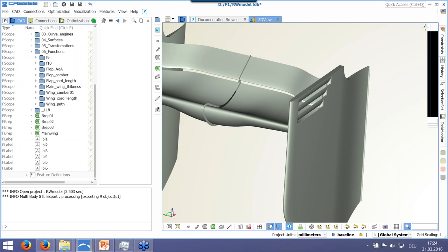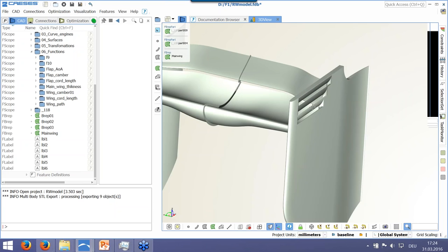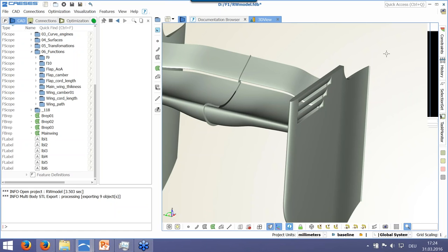Okay, and why we use these louvers or these slots here is because when you open these slots, a quantity of the air will go through from here. So we will reduce the delta P, or the difference of pressure between here and here, and this has a significant influence on the strength of this vortex. So this will really reduce the induced drag. So for this reason, they use the louvers.